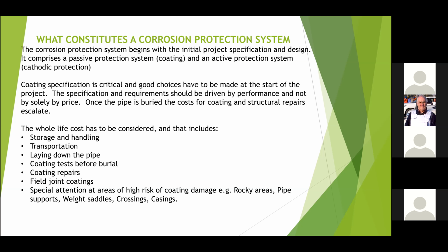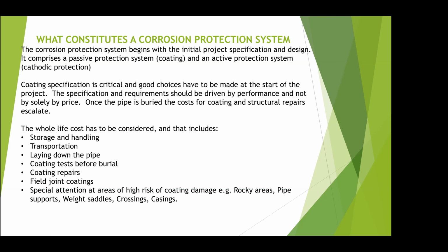And then you need to pay special attention where you've got a high risk of coating damage, such as rocky areas, pipe supports, where you're pulling the pipe through the soil, through a thrust bore, where you've got crossings and casings, all these sort of things. You need to take care of that. That's part of the system.